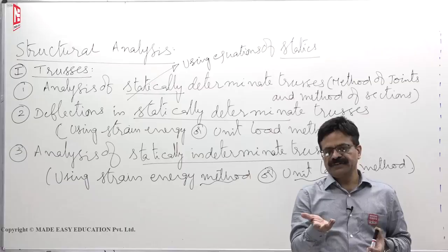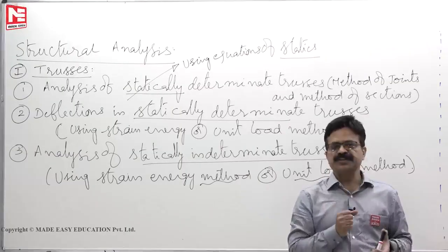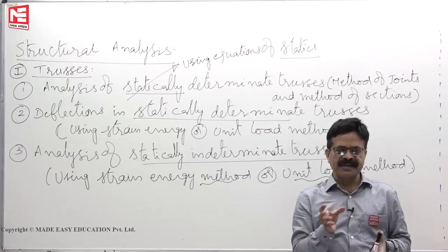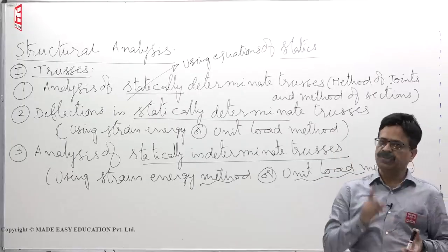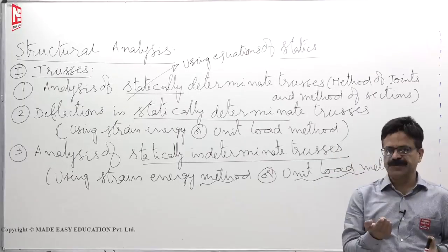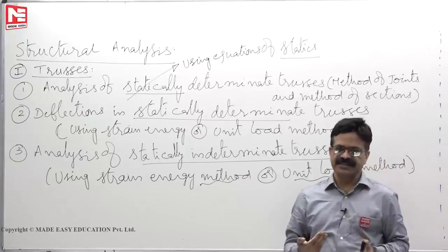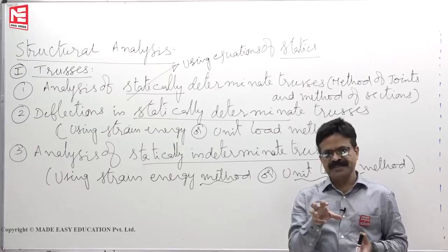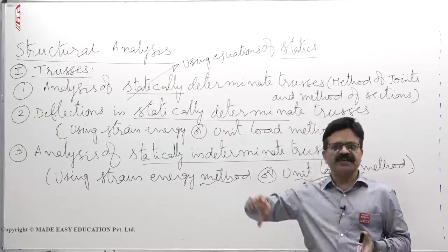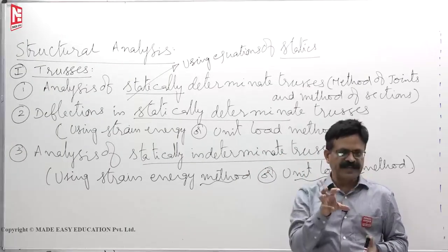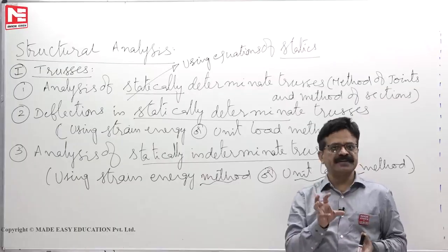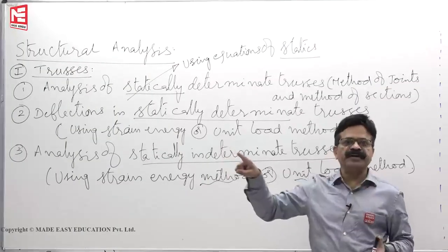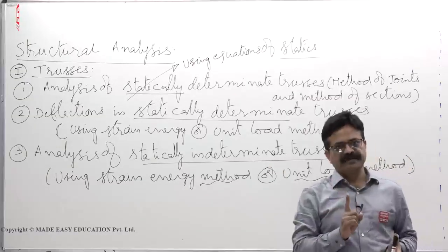Then after that you have studied flitched beams in the theory of bending stresses chapter. They are statically indeterminate to 1 degree. That means DS is 1, so one compatibility condition is required. What compatibility did you use in flitched beams? The radius of curvature of the bent steel beam and the radius of curvature of the wooden beam must be equal, because both bend like a single element.